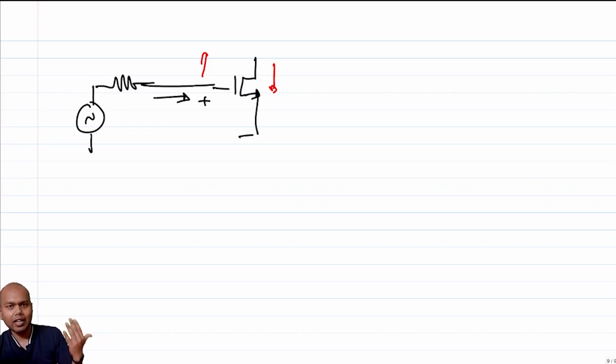So in order to get a lead, I have to use something which goes up at a faster rate than a resistor, which means that I need some frequency dependent component, and a capacitor doesn't do it. What else can I put? Resistor is ruled out, capacitor is ruled out. So the only other thing is an inductor. So let's try with an inductor, right? We'll put an inductor here.